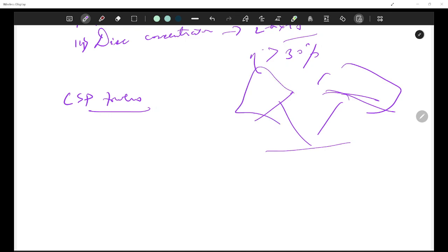So the limitations of existing heliostats are what? If you remember, wind loading causes deflection, requires heavy structural backing, and it also requires expensive speed reducers. The sun moves only at 15 degrees per hour. It is very slow. We need very precise motion.